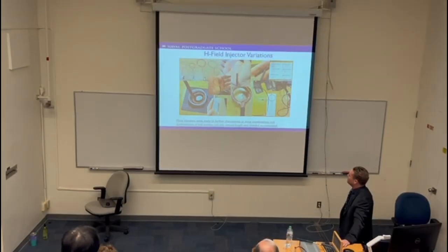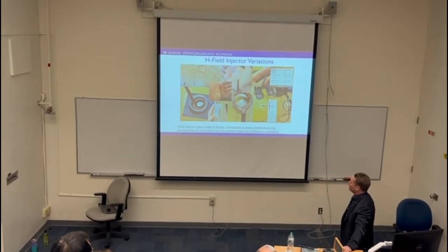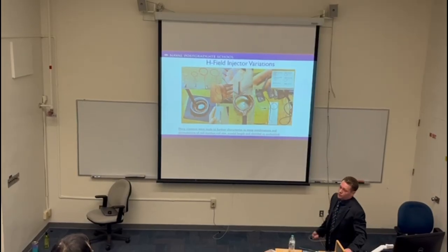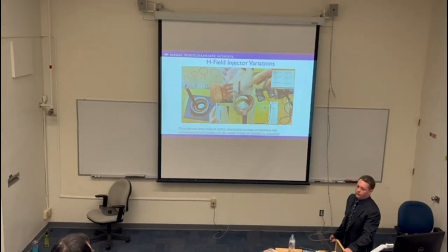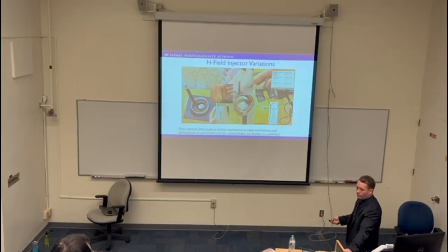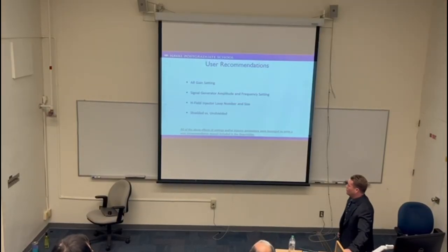There's a lot of different injectors, epoxying them, shielding them, shortening them, lengthening them, and we wanted to see if there was any of this information we could use to leverage from a user standpoint, right? Because somebody at the end of the day has got to use this, and they want to know, okay, I got to inject this type of H field into this type of system. What would you recommend? So that's what we put together.